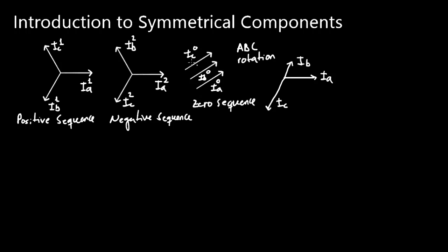And this is pretty typical. This is usually what people use in industry. Sometimes you would see just a positive sign on the positive sequence set and a negative sign on the negative sequence set. But for the most part, people use 1 for positive sequence, 2 for negative sequence, and 0 for the zero sequence. And so again, the concept of symmetrical components is just a mathematical tool that we can use for our analysis of unbalanced power systems, such that we can analyze unbalanced faults, for example.